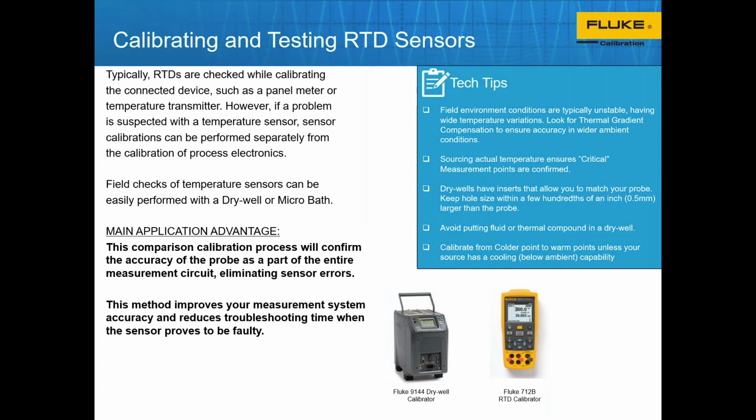So we will insert the probe in there and measure the actual output from the RTD itself. We'll measure resistance as an example and then compare that resistance to a table, or we will use something like a Fluke 712B or a 714B, or one of our other multifunction or documenting calibrators that can take the actual raw thermocouple and RTD values and convert them into the actual degrees C or degrees F on the display. These devices contain all of those lookup tables for you. That's how you get your accuracy, and if it's been calibrated, that's how you get your traceability.